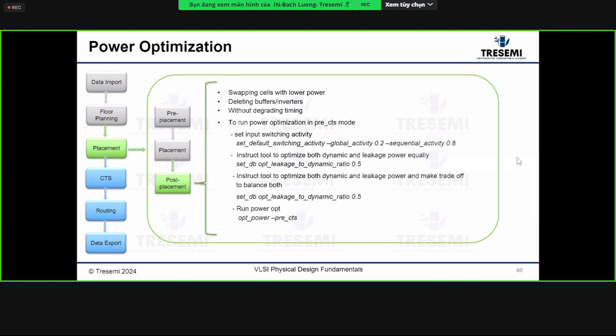So this is different than the other page where you set the switching activities on the primary input and let the tool calculate the internal switching activities. Over here, you say set all the internal nodes, 4 billion of them, each node switch 20%.